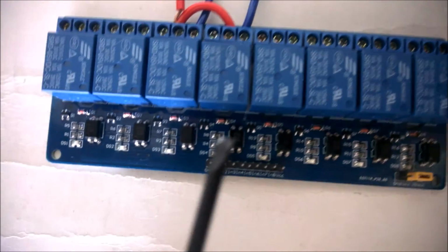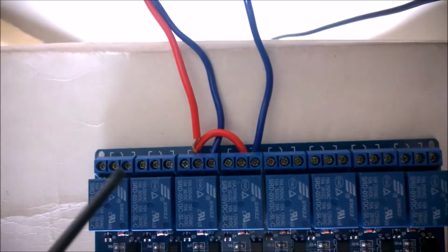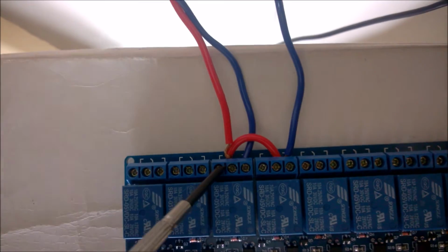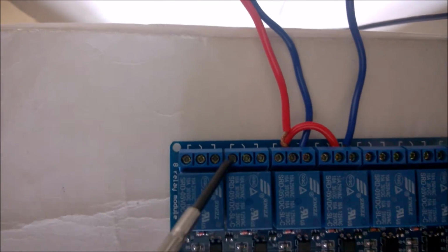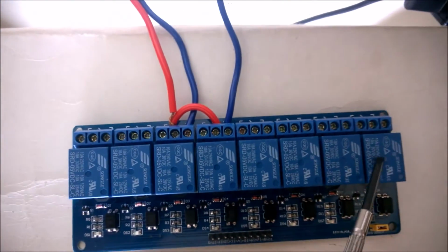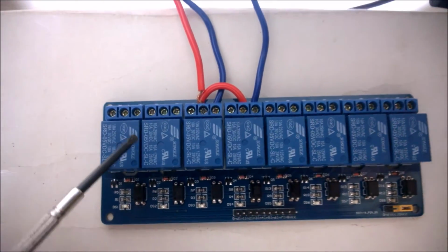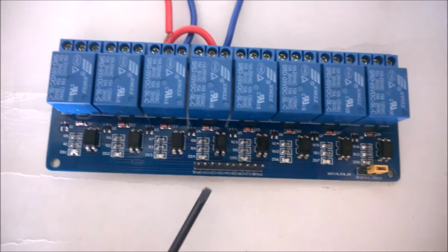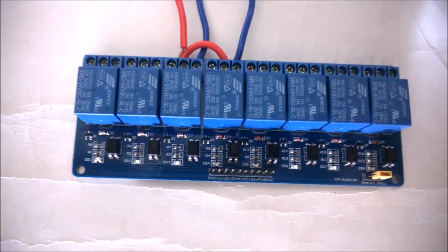So what we will do is give the input from the Arduino over here, and then you will connect the wires from the switchboard to these ports. If you see here, there are 3 ports for each relay module. So this one is a relay module and this one is a relay module. Like that you'll have 8 relay modules, 8 relay switches, so this one is called an 8 relay module. For each relay module, you have a corresponding input over here, so you get the output from the Arduino to here.